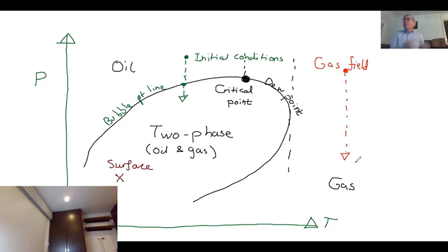End of story. And because we start with a pressure that's typically hundreds of atmospheres, we can't go all the way down to 1 atmosphere because then there's no driving force for flow, but we can normally go down to a few tens of atmospheres. We can have a 95% drop in pressure. Because roughly speaking, and we'll do this more precisely in a moment, the amount of gas, the mass of gas, the moles of gas for a given volume is proportional to pressure. We can have a 95% recovery. Okay, so that's pretty good.